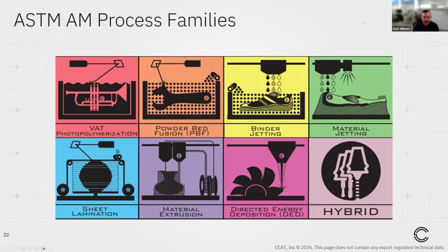And we have hybrid manufacturing on there as kind of a fun addition. And hybrid manufacturing is a newer trend, I'd say, within the last 10 years or so. We can look at machine makers like DMG Mori, who are making combination machines where we are incorporating both that additive build capability along with, let's say, the capability of a 5-axis CNC machining center. So within one machine, we can actually build up material, machine it back down to conforming geometry.